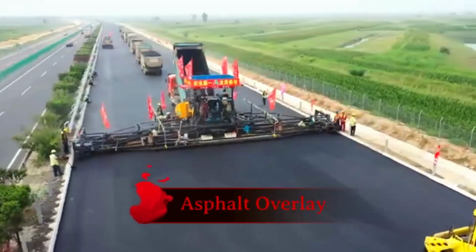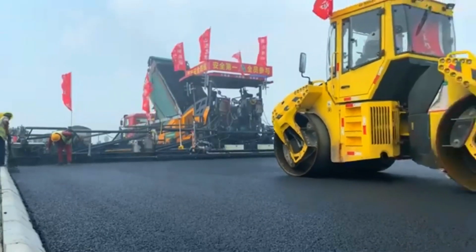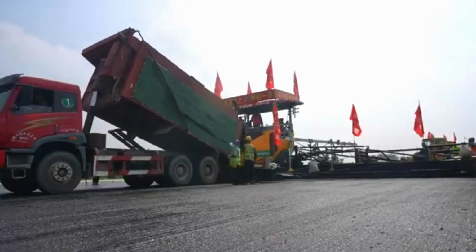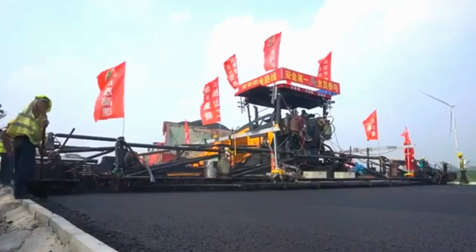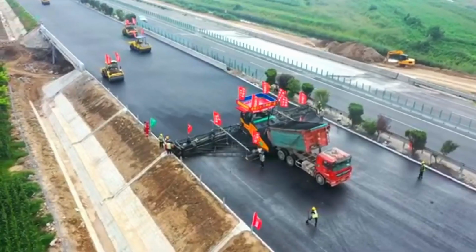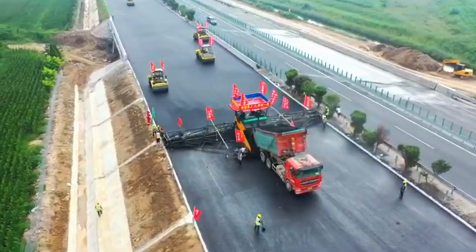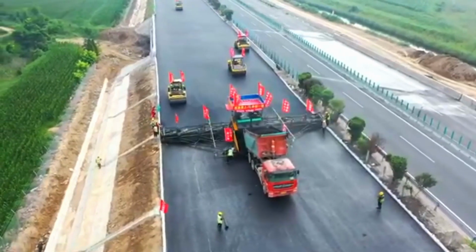Step 4. Asphalt overlay placement. Once the surface is ready, the new asphalt mix is laid using an asphalt paver. Hot mix asphalt, HMA, is transported from the plant and evenly spread over the road. A paver screed levels the mix, ensuring uniform thickness and smoothness. The overlay thickness typically ranges from 25 mm to 75 mm, 1 to 3 inches, depending on the pavement condition and traffic load. The new asphalt layer improves ride quality, restores skid resistance, and enhances durability.